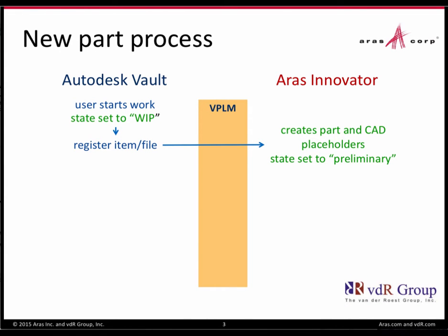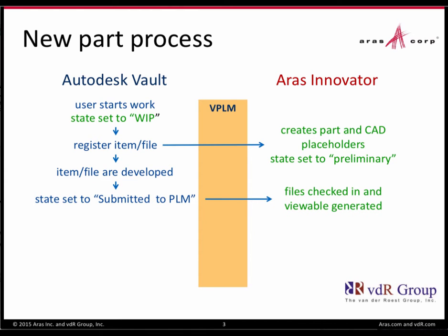So far we have checked in the files to Vault, registered them in PLM, submitted the files to PLM where all the parts and CAD items are synchronized, part bill of materials recreated, CAD structure preserved, and viewable files made available to all PLM users. We will now complete the new part introduction process by using the PLM workflow tools.